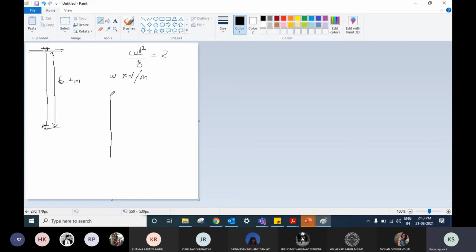One thing is the main soil to be retained. It puts a lateral pressure called active earth pressure on the retaining wall, right? So I suppose this wall is retaining the soil, right? I'll just mark it so that there's something like soil over here. Now it is going to exert a pressure. That will be a triangular distribution because the more the depth, the more will be the pressure, right? So that's the thing with the pressure head that we assume in water forces calculation and things like that.